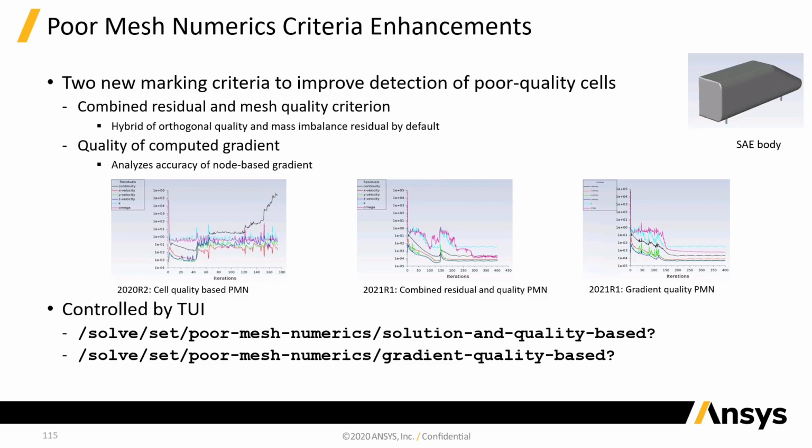At poor mesh, typically you would either revert to doing a first order solution, so upwinding, or if it's really severe, a zeroth order solution where you basically just do a bit of local averaging around that cell and put the average value in.